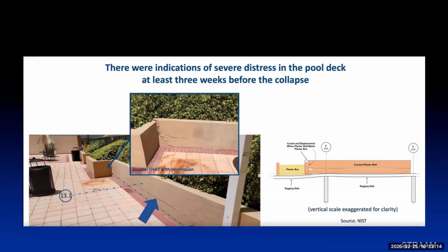So in other words, if you're doing a visual investigation, you have to be aware of small signs like this. You need to know what causes a horizontal crack. In this particular case, it was fundamental to the entire collapse occurring.